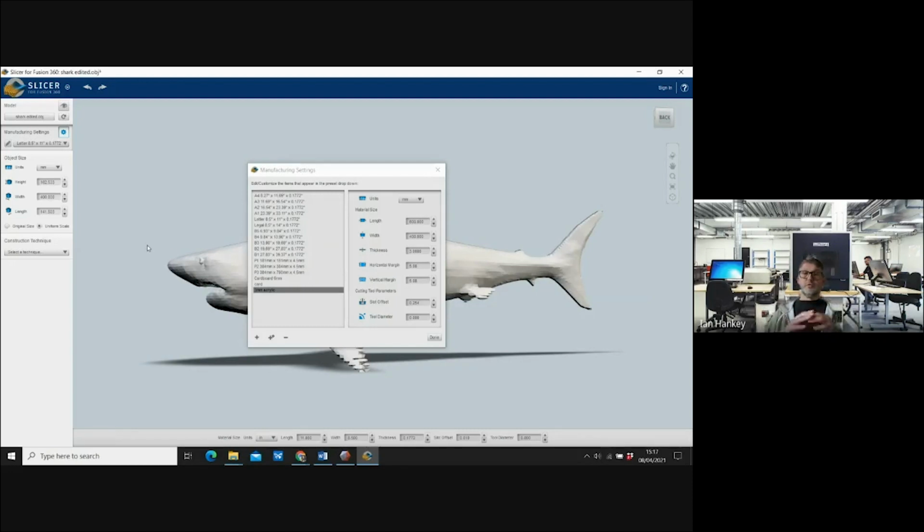So we're going to add a new material to these manufacturing settings. You can see there's a plus there, on the left-hand side. So I'm going to left click on plus, and it opens up an unnamed tab. And I'm going to call that, if I double click on it there, and it's gone dark blue, so I can type in what I want, plywood.